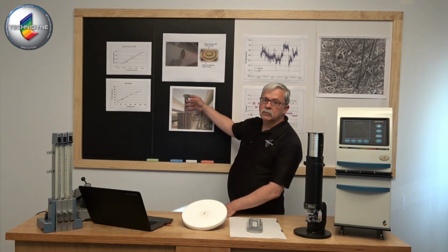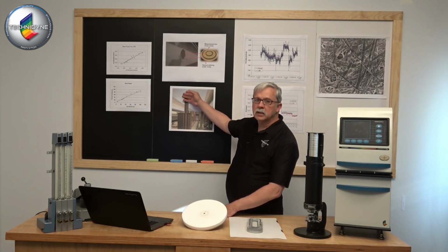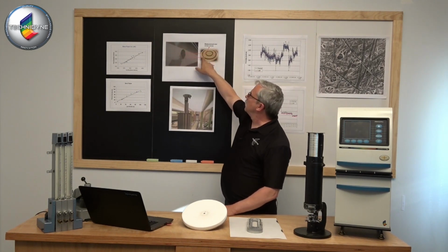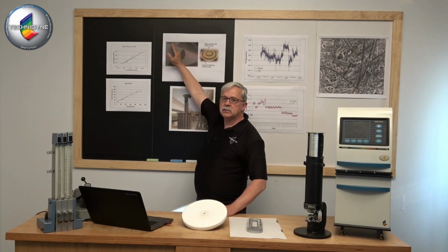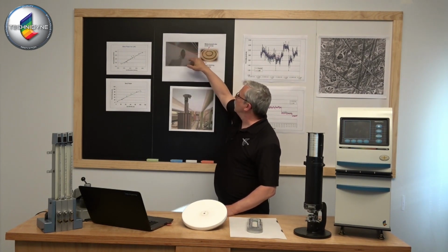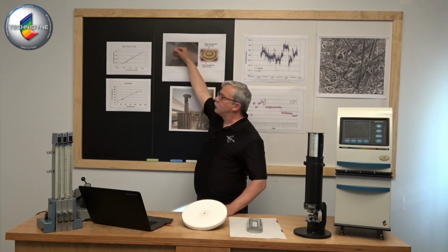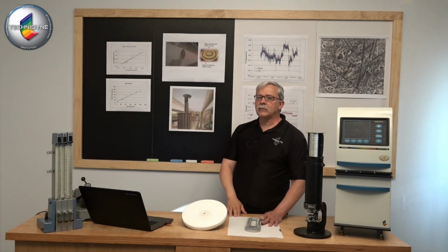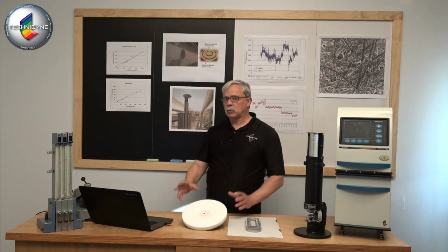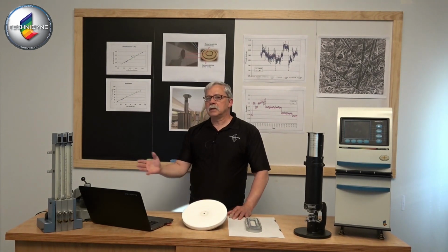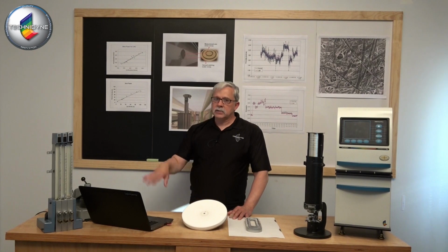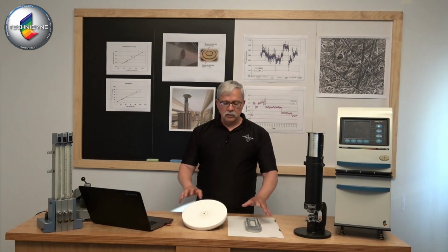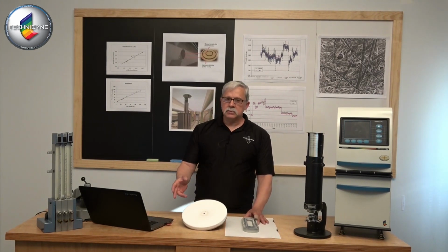So we have this mounted underneath the web. This measurement head is actually in contact with the web. I don't know if you can see my shadow here, but again, the outer ring is drawing the web to the measurement head to seal it tightly. The inner ring here is drawing air through from the atmosphere and then through our measurement system, and then we use it to evaluate and send that information to a control box. That control box could easily be connected to a DCS system so that you can interface it with your mill system.